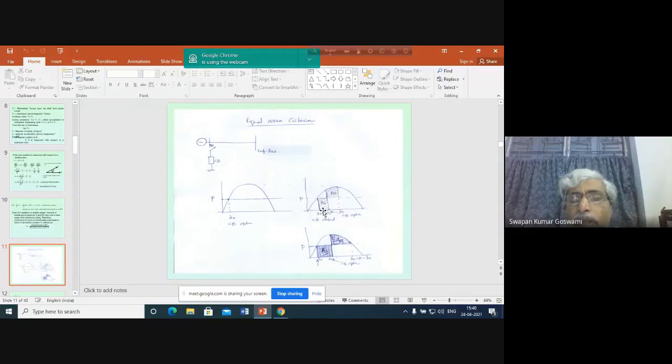This area A1 represents an energy, and this energy is actually inserted into the rotor of the generator. Mechanical power is being delivered from the outside, but output power becomes zero. So this power will obviously be stored in the form of kinetic energy of the rotor. So rotor speed increases, delta increases.